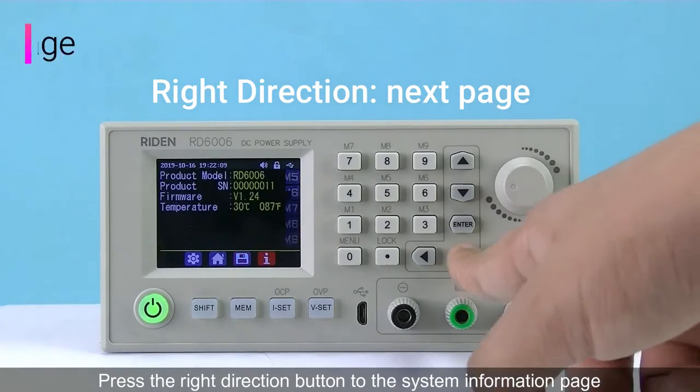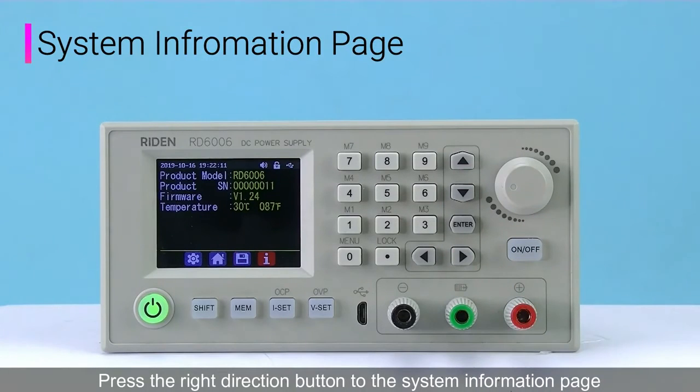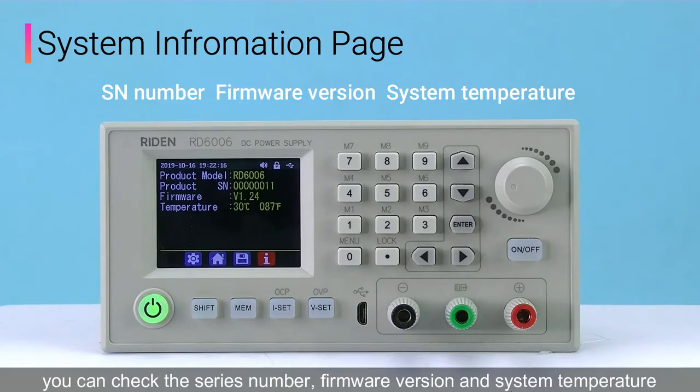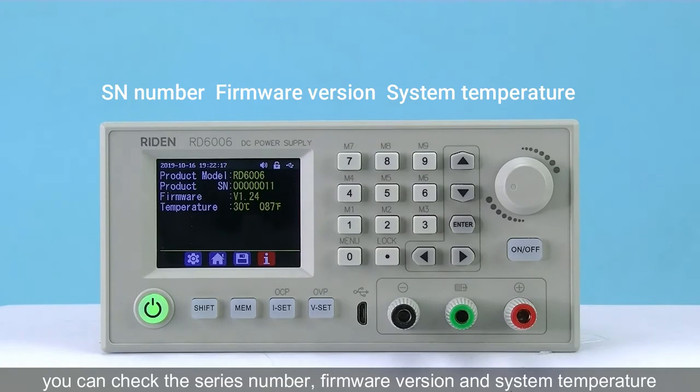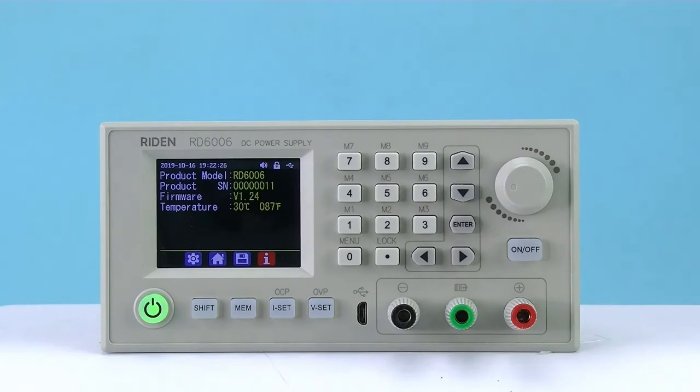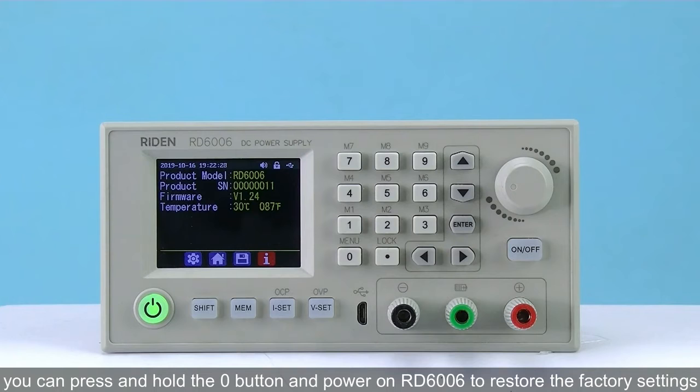Press the right direction button to the system information page. You can check the serial number, firmware version, and the system temperature here. If a wrong setting causes the system to work abnormally, you can press and hold the 0 button and power on the RD6006 to restore the factory settings.